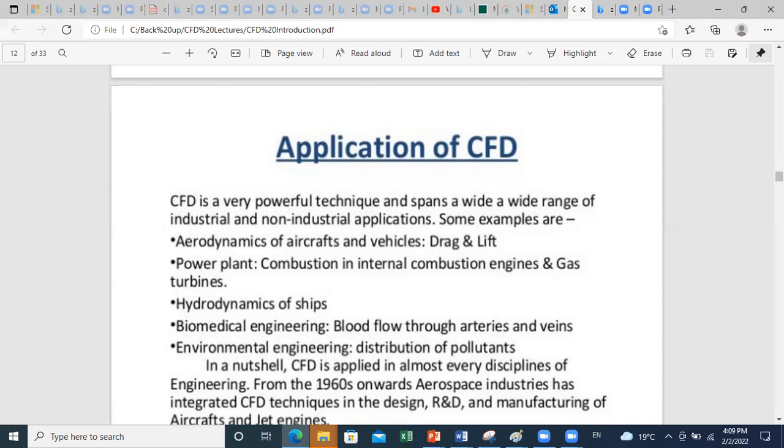It can also be used to know what type of materials should be used when designing our systems, because it allows us to study the pressure field over the car. So we can compute the maximum pressure zones and determine what material is convenient to use at these locations.